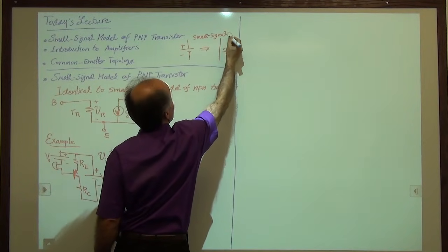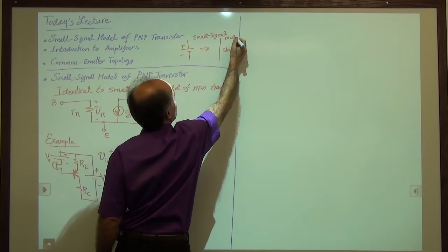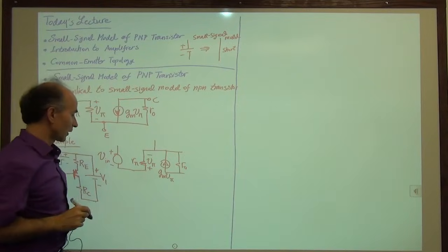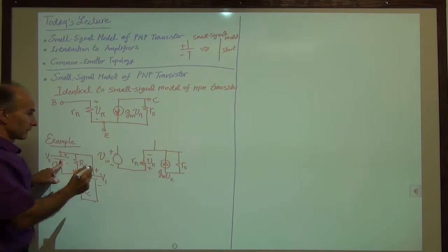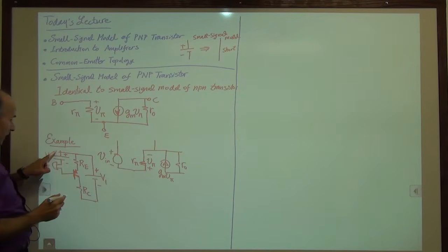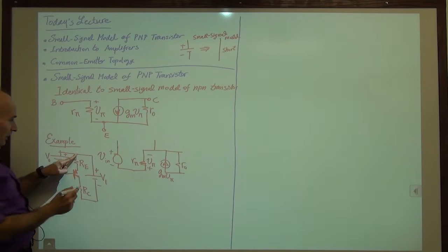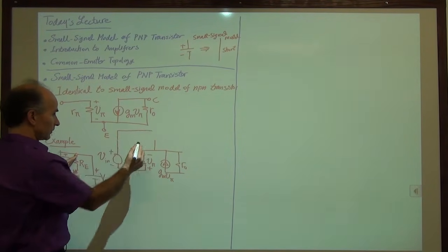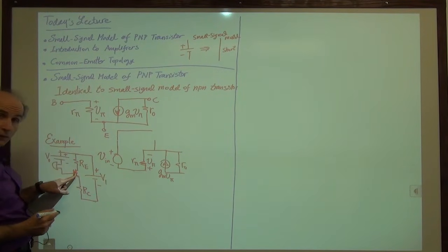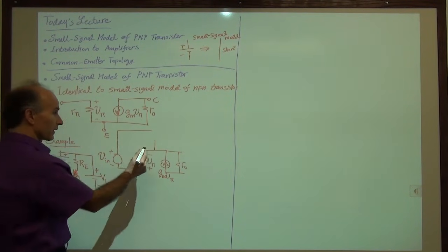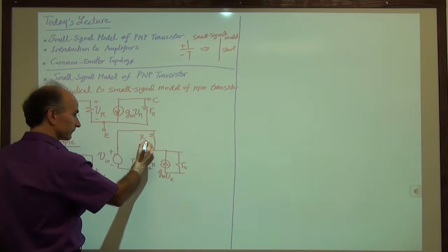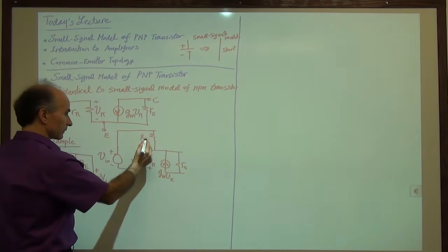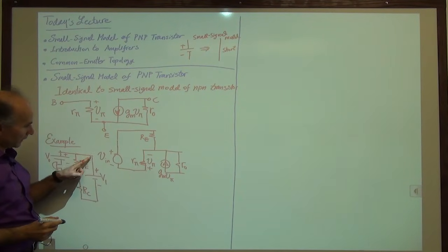Small signal model. Okay, so we will replace this battery by a short circuit, just a wire. They come up here. There's another wire that connects this point to a resistor that goes to the emitter. So here's the emitter. We connect our resistor RE, and we continue. Now we go over here.